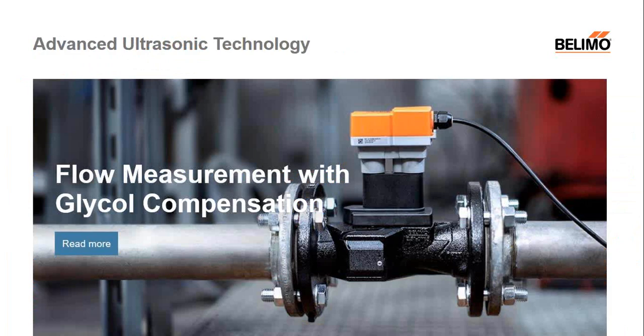This gives us a lot of good advantages. It gives us temperature and glycol compensation built right into each of these flow meters. So as temperature and glycol concentration change, we maintain our accuracy with this product. We've seen statistics that show up to 30% deviation for sensors that do not have this capability built into them.